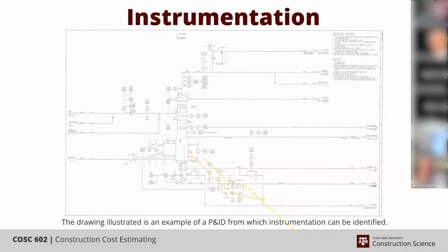But either way, if the whole system's designed to handle, say, 120 psi, that thing will be designed to fail at 118 or 119, something really close, but just before the system goes. It's better to lose that in a controlled manner, in a location that's designed to handle the release, than it is for the system to fail as a whole. That can be extremely detrimental. It relieves into that pipe to the flare, probably not to atmosphere though.